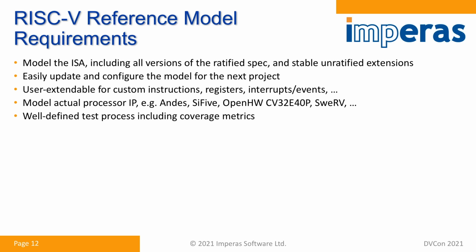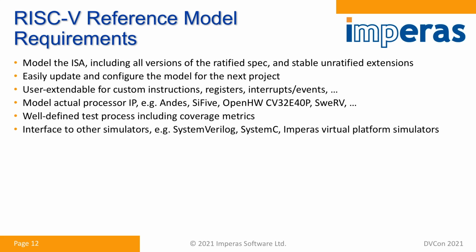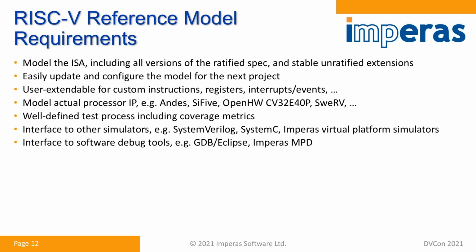There needs to be a well-defined test process, including coverage metrics for the reference model. It needs to be able to interface to other simulators, whether SystemVerilog, SystemC, or even virtual platform simulators. Because the reference model might be used first for design verification, but you're going to use it for other things like software development. And while it seems obvious, it still bears mention that there is value in a common platform for verification and software development.